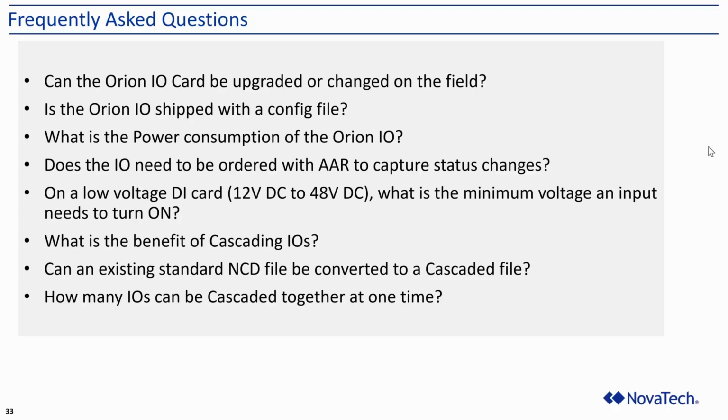On the low voltage DI card, the one that's from 12 to 48, what is the minimum voltage input needed to turn that input on? It's above 9 volts. Anything above 9 volts will turn that contact on.